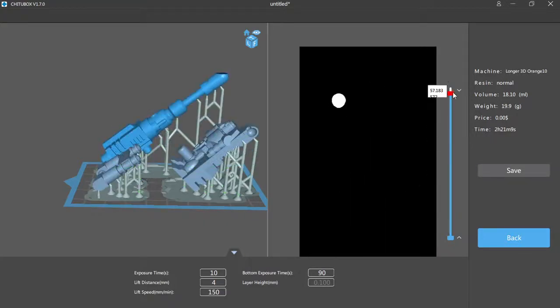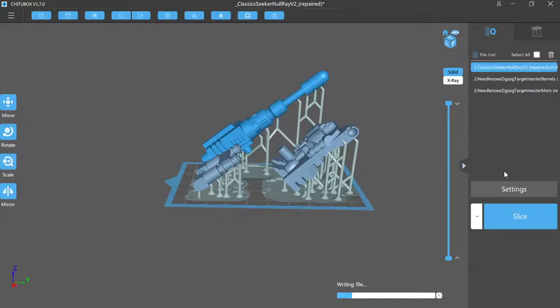That's pretty much it. Now, again here, this is an area where people were getting confused. You can click save, and it doesn't show you anything. It doesn't show you that dialog. But if you just push enter, it will go ahead and write the file to where you started, and it's using the very first file I opened as the name for the file. It just creates an underscore and uses the file name from your original model.